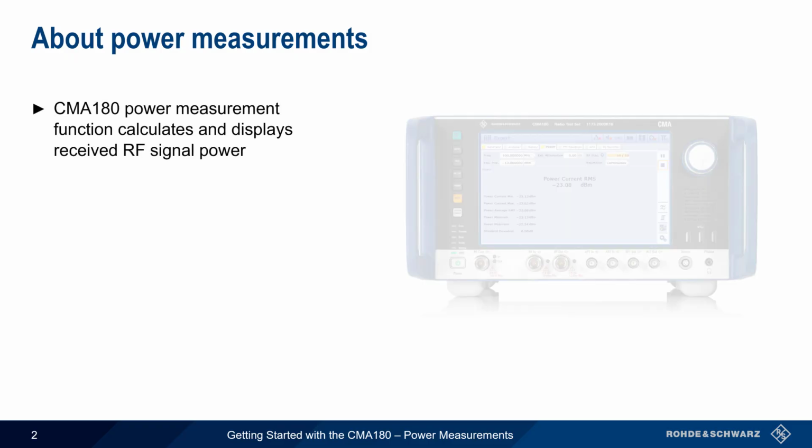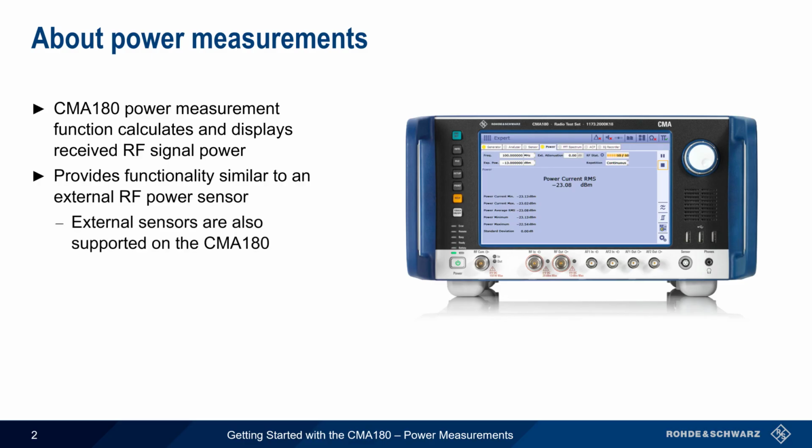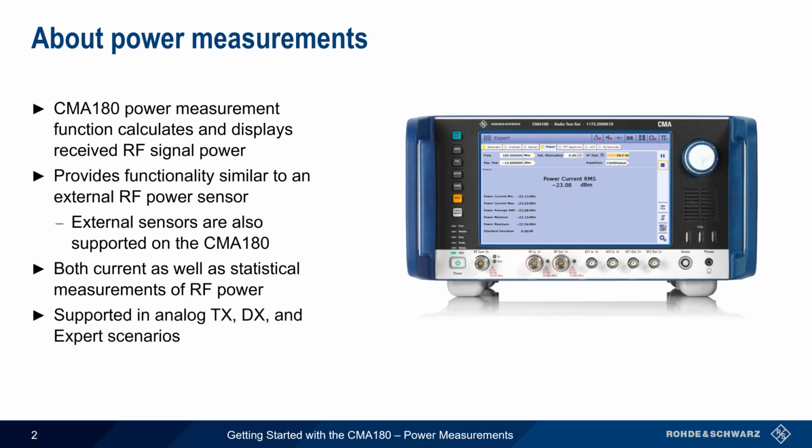The CMA180 power measurement function calculates and displays the received RF power level and provides functionality similar to that of an external RF power sensor. Note that external sensors are also supported on the CMA180, and this is covered in a separate presentation. The integrated power measurement feature provides measurements of both current RF power as well as various statistical measurements, and this function is supported in the analog TX, DX, and expert scenarios.